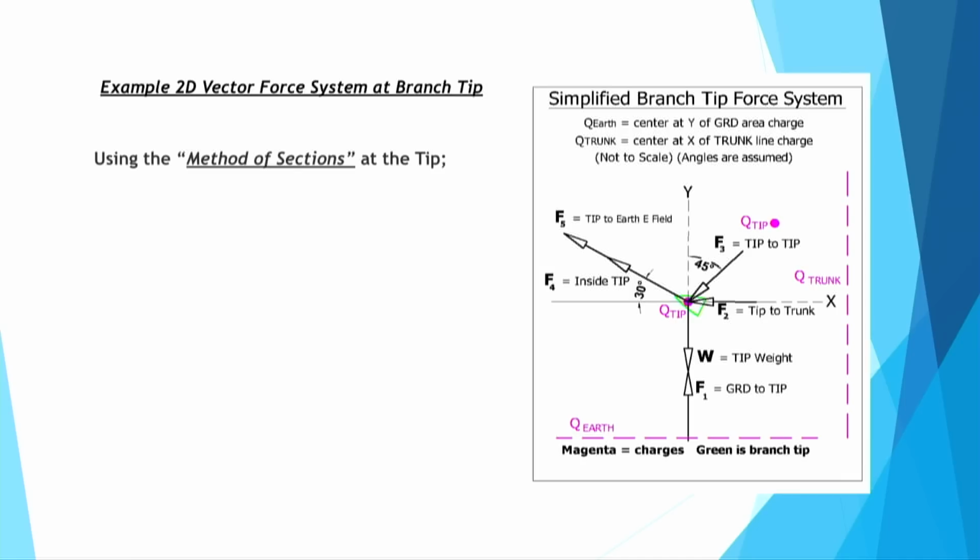So I use what's called the method of sections at the tip, and that's where you do an imaginary cut across the tip and then you apply forces to the tip to bring it into equilibrium. That's an engineering trick that engineers use. What I didn't do here was show a shear force and bending moment, just to keep it simple. So there's only axial forces shown here.